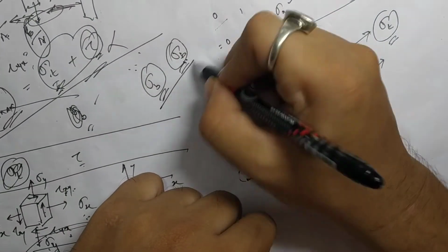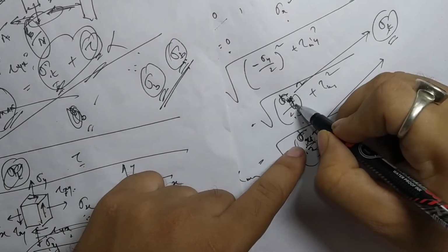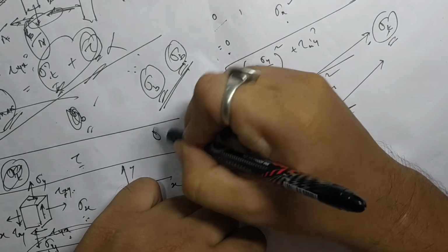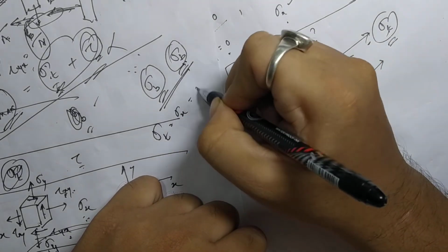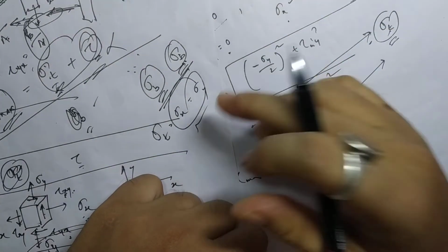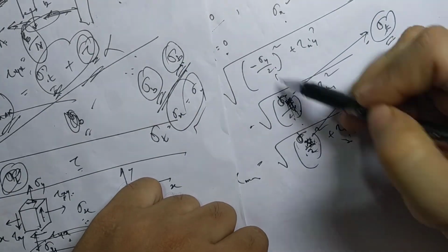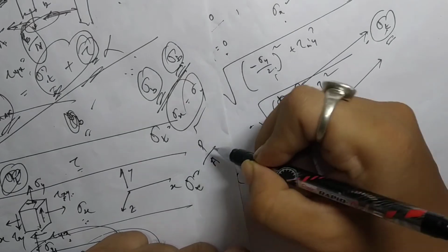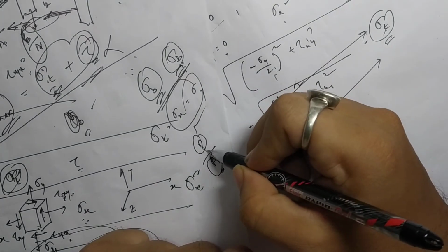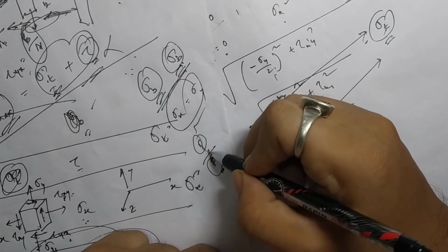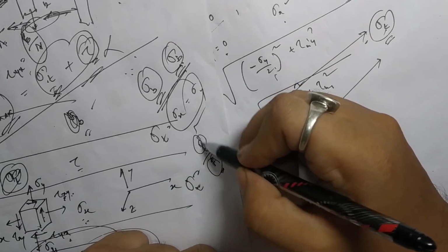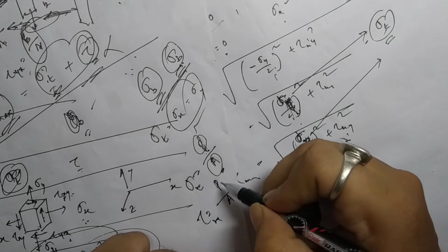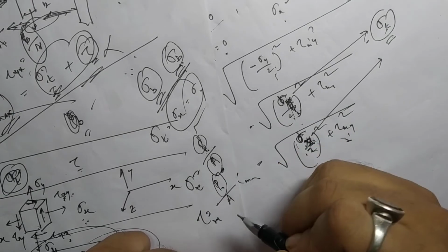Okay, so now see, tensile stresses are here. For tensile stress, you'll put either sigma x or sigma y, anything you like you can write, but only one is there. That means sigma t is what? This force by area. This area is the perpendicular area, and the force is the force along the axis. And tau xy will be force by area only, but this force is now the shear force divided by the area.